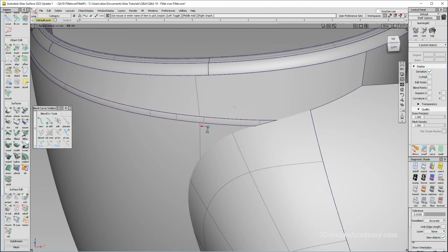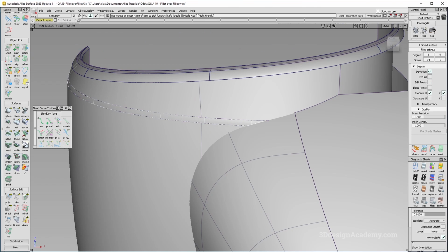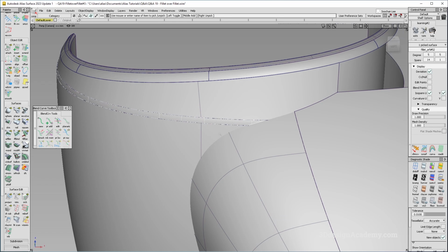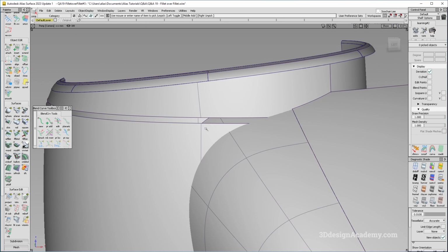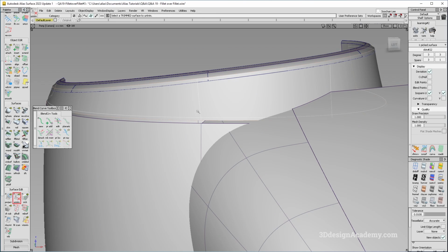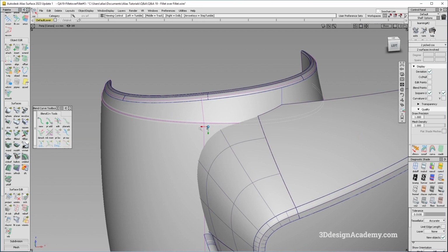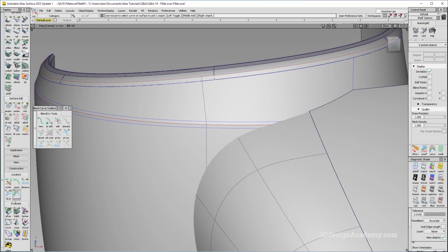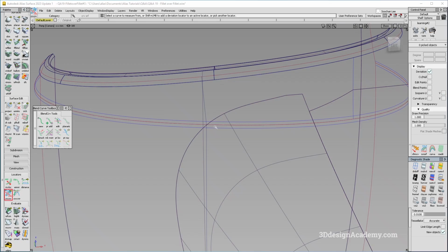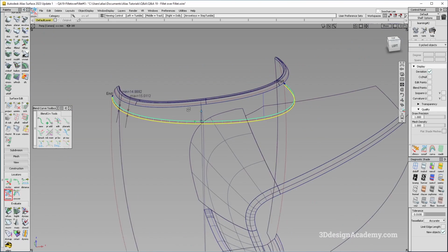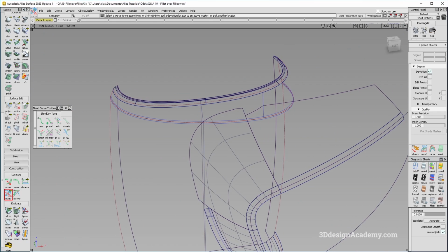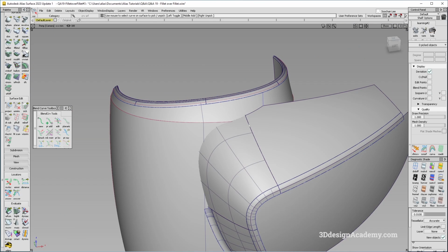But before that, I am going to build a larger one first. In order to do that, I'm going to split this surface over here. So let's go ahead and do that first. I'm just going to delete that one, and let's untrim this surface over here like this. I'm going to untrim this one over here like this, and let's go ahead and delete. Oh, actually, before that, let me take a quick measurement. Okay, so it looks like this is 15. All right, so I'm just going to delete the COS over there.